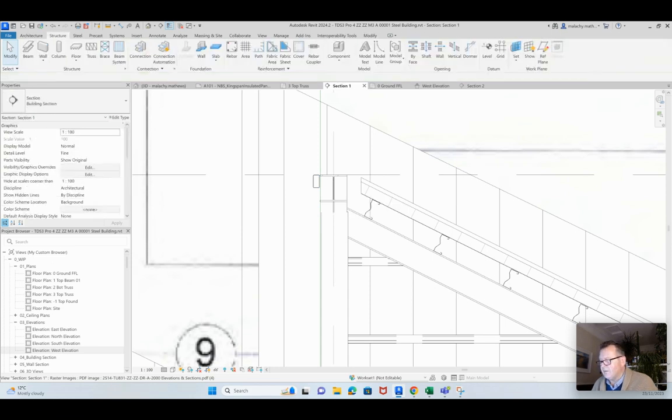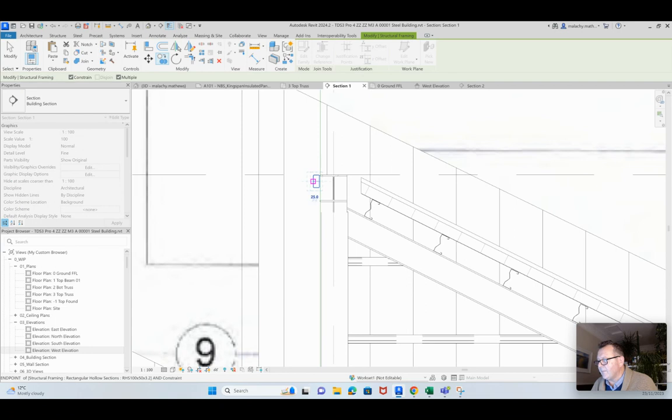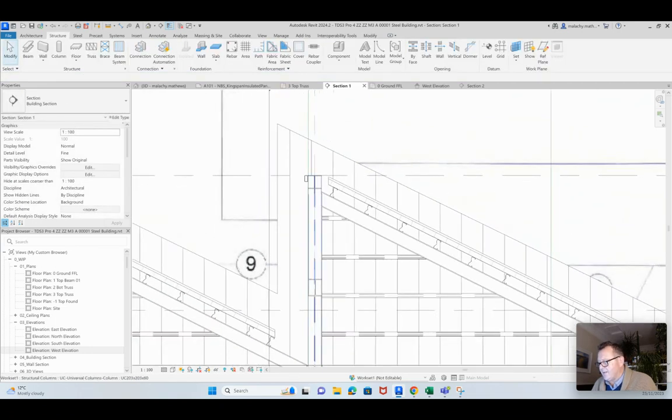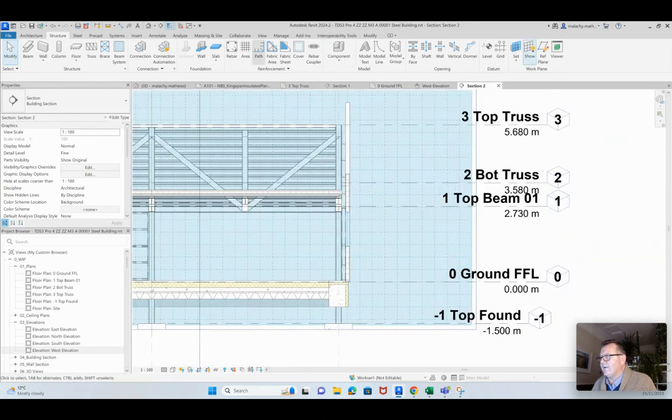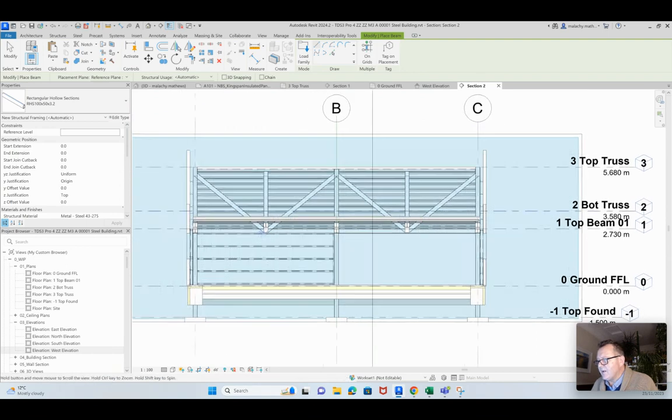I don't know if it'll allow me to copy down, will it? No, it'll allow me to copy across. So I wanted another one down in around here, possibly a third one down here for that. Is that big enough? Maybe. Yeah, it's not too bad. I don't want it to stick out too far because remember, I'm putting the wall in there as well. So we're back to here and we'll do that again. Beam, there's the C channel there.